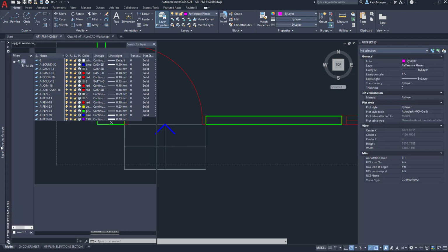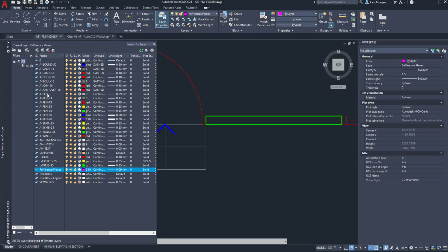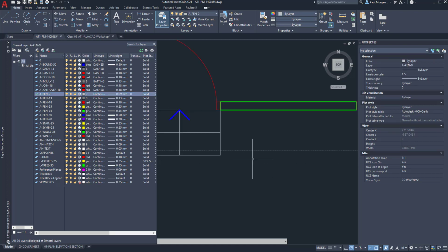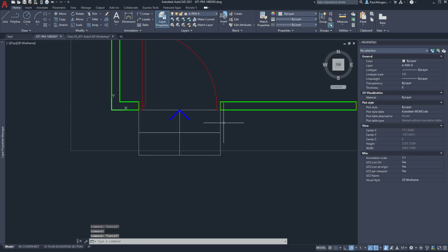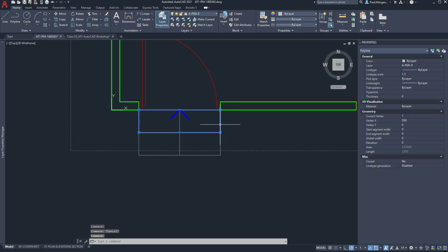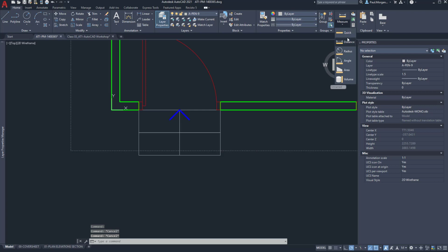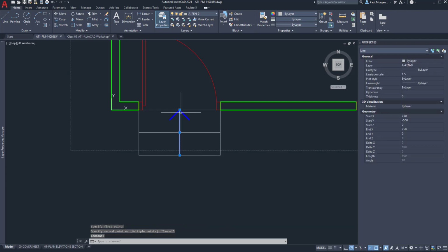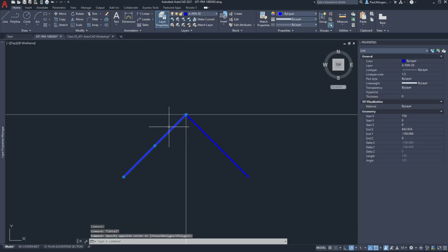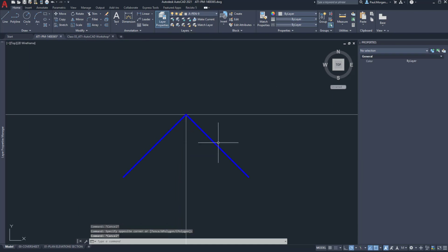So I'm going to go back to my properties manager and go to my Pen 9, double click on that, and then it was simply just drawing two polyline rectangles. Each of them, let's see how thick they are. One step is 250 mil, which makes sense. That's the Australian National Construction Code requirement. So 2 steps at 250 mil each, and then I just simply have a pen 9 line for the arrow, and then the arrow head is thicker, and that's using an A pen 50.